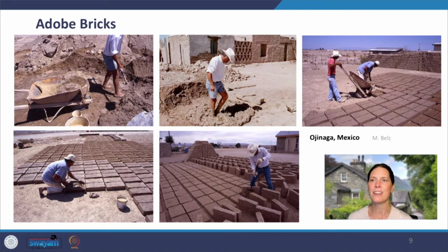For plaster, it has to be elastic and sticky enough to stay on the wall while not cracking significantly. Yet it can't be too sandy that it brushes off to the touch. Milk, animal dung, wheat flour, plants, and colored clays are all often added to the adobe earth mix to bring about more desirable qualities, whether for the interior or exterior, such as hardness or color or sheen.